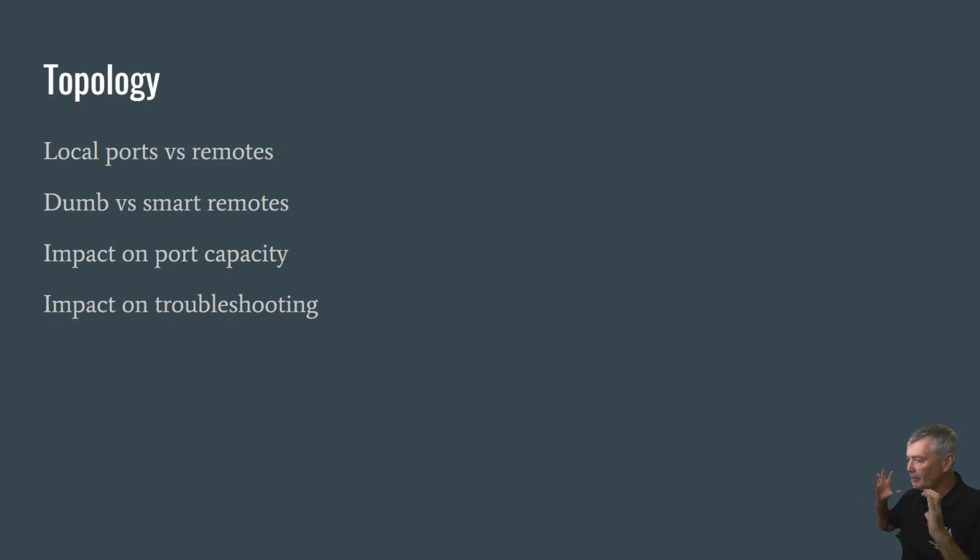Now, there is a lot of complexity here as it relates to how these remotes impact on your pixel port capabilities. You know, controllers will talk about, I can run 680 pixels off a port or 1024 pixels off a port. Adding these remotes generally subdivides that pixel capacity up across the remotes.